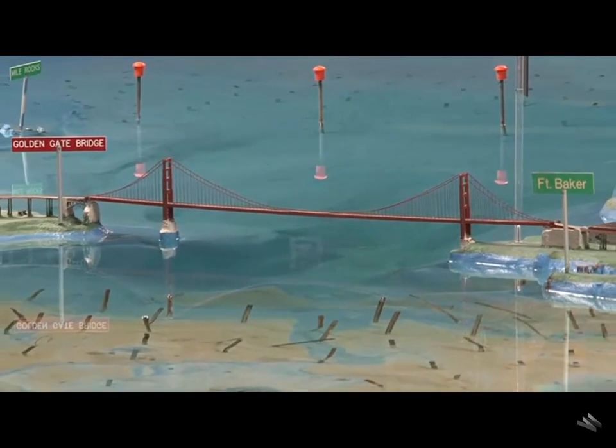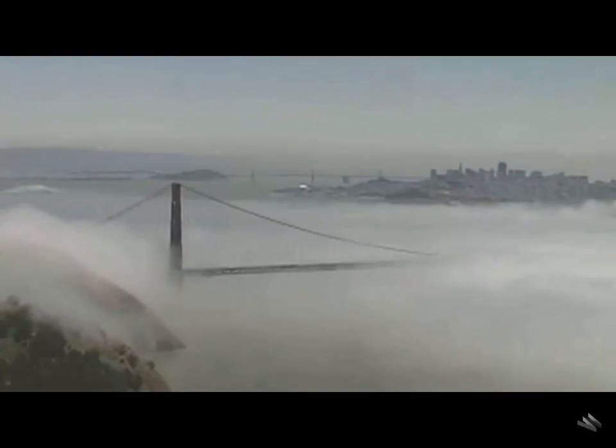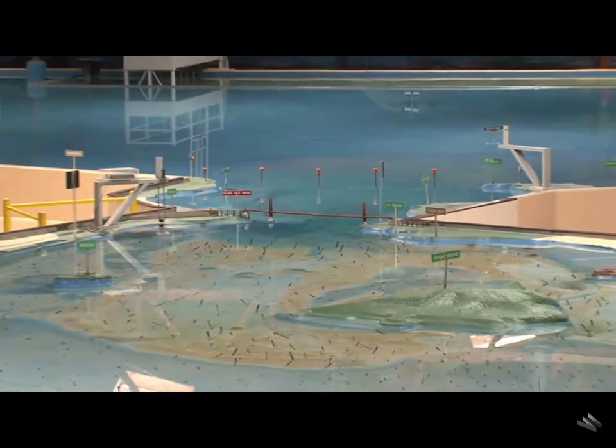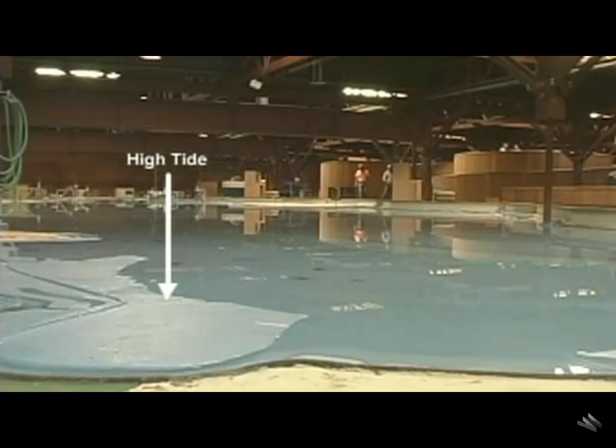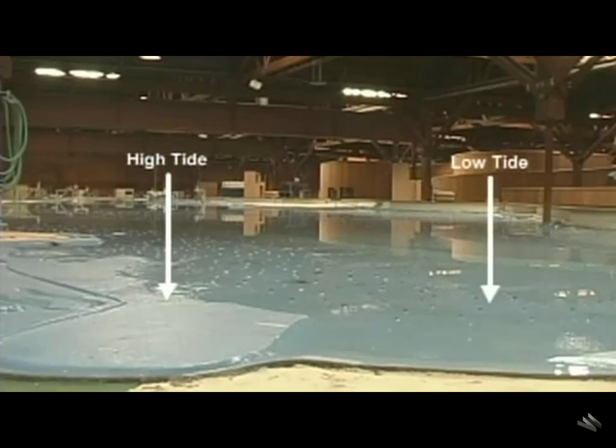The vertical scale is 100 to 1. So for every 100 feet underneath the Golden Gate Bridge, 1 foot down in the model. But the most important factor is time. Now a lunar day is like 24 hours, 54 minutes, so many seconds. But in the Bay model, that happens every 14.9 minutes. So every 14.9 minutes in the Bay model, you have 2 high tides and 2 low tides. Mathematically, it's changing about every 3.78 minutes.